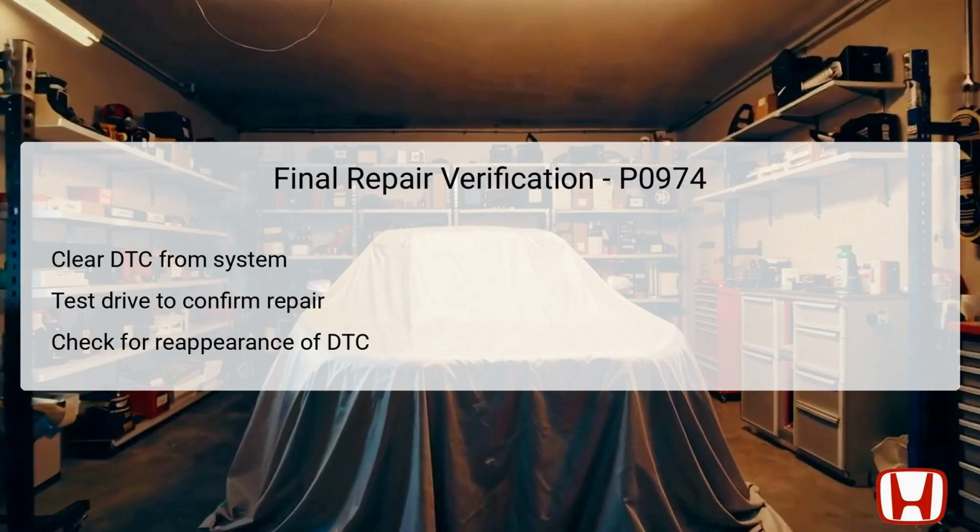After the test drive, recheck for the presence of any DTCs. If P0974 does not come back, this suggests successful resolution of the underlying problem. Monitoring the vehicle post-repair is essential to ensure that the repair measures taken were effective.